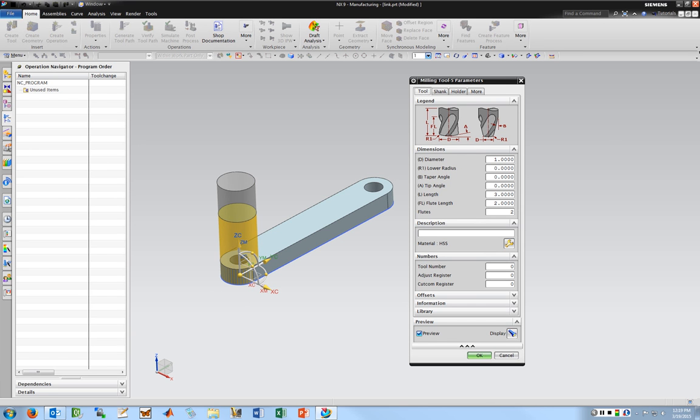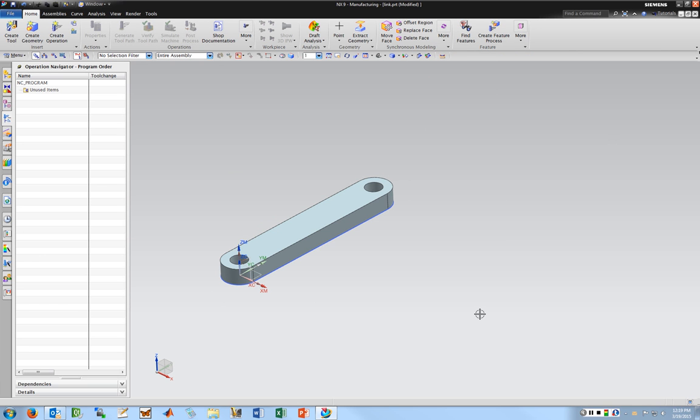What I do need to set is the tool number. So when I actually set the machine up, I'm going to have tools in the different tool stations, and I'm going to have offsets in the machine, things like the vertical height offset and the cut comp, which I generally don't need when I'm machining this way, but I'm going to go ahead and set all of these to 1. So whenever I load this actual tool into the machine, it's going to be at station 1. You can see some of the offsets and other things here, which we don't need to change for now. So that looks good for what I need to do. I'm going to go ahead and hit OK, and I've got an end mill. So let's do something with it.